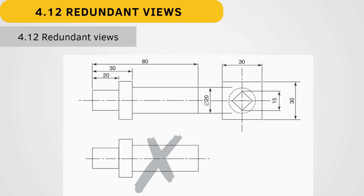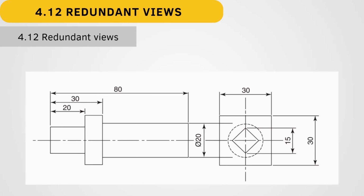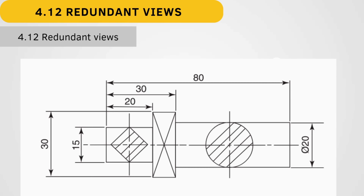This is an example of redundant views. From this first angle drawing, the top view is the same as the side view, so it is reduced to two views, the side and the front view. After that, the drawing is reduced to a single view by using a revolved section and BS convention for the square flange.